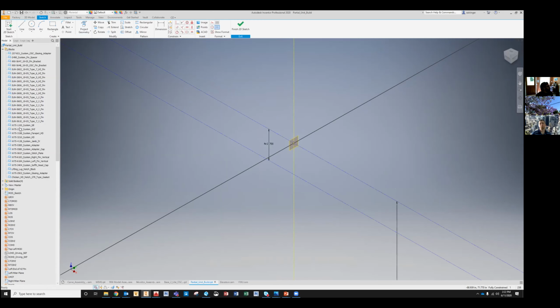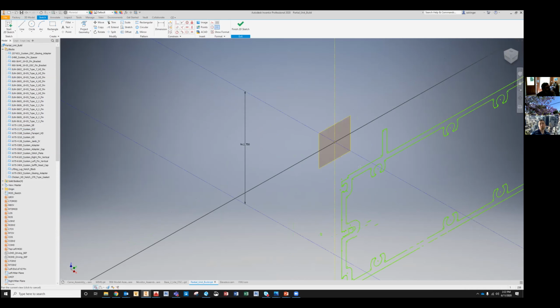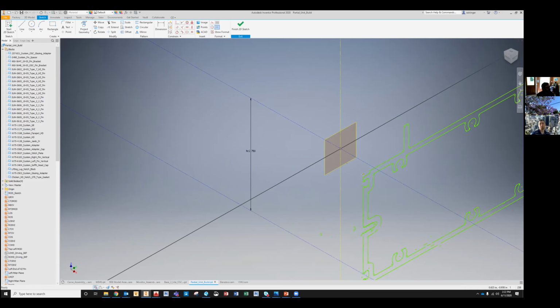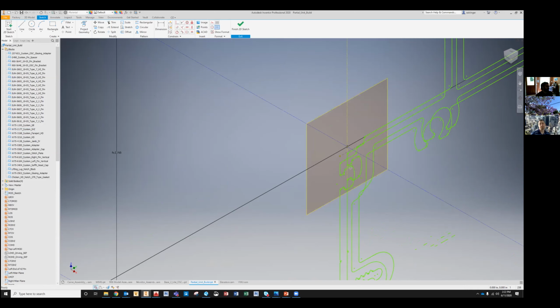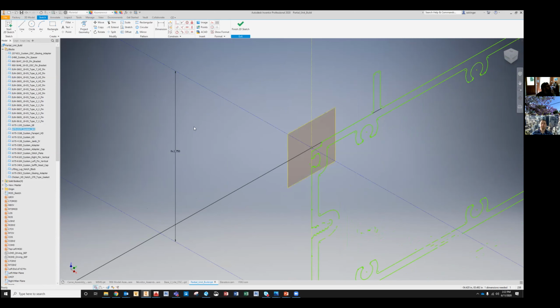Then you can come over to this browser and right click and then go place block. Another plus side of the blocks, if you use place block, is if you've created an insertion point, you can hover over until the dot turns green and then click, and that actually creates a constraint right away.